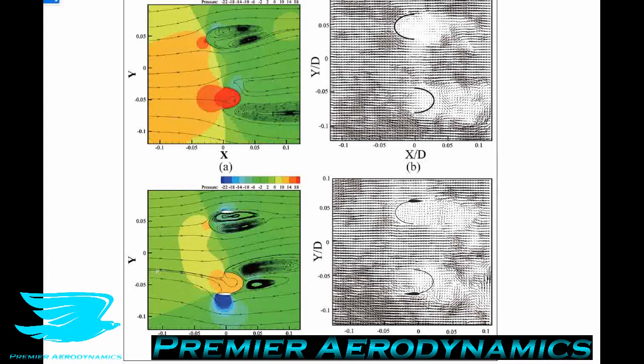and that makes sense, kind of, because if we look at the flow coming in to this airfoil, we can see it's skewed. So effectively this airfoil is seeing a non-0 degree angle of attack. The effective angle of attack is not 0. So that means that this airfoil is producing some amount of lift, as we can see by this low pressure on top, high pressure underneath. So that's why we get this change here.